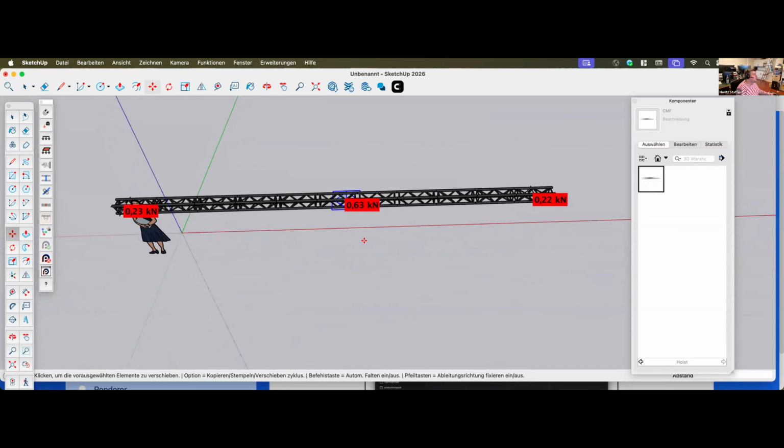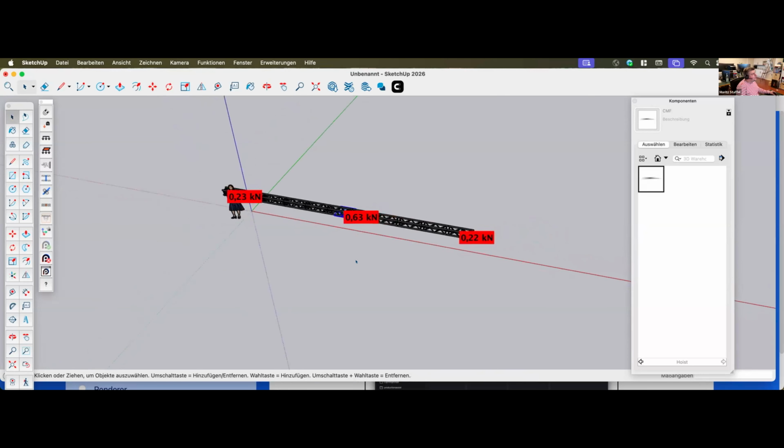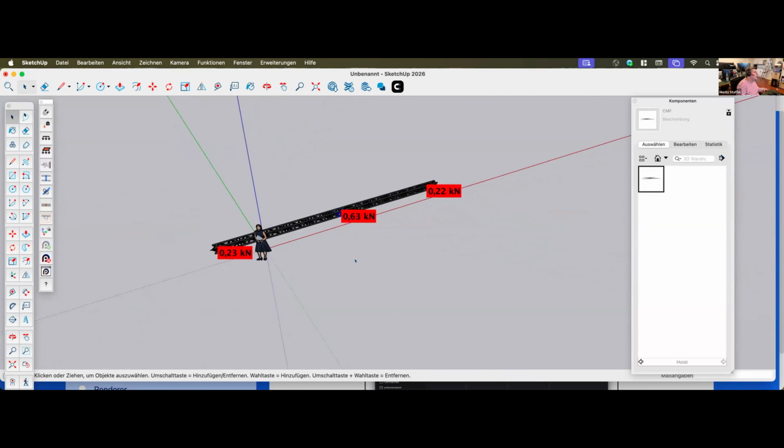So now when we are doing the calculation in here like this, I actually see that I have a distribution between 3 points. Typically about 66% go into the middle if you have 3 hoists, and about 18% go into each of the outer two. In other words, almost 3 times the load goes into the middle and 1 time goes into each outer side. So we see it's quite easy to reproduce the results that we want to achieve.